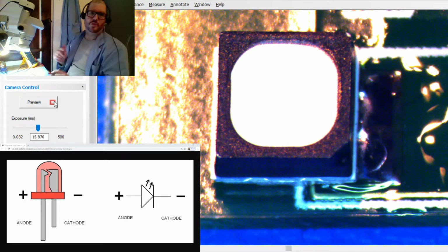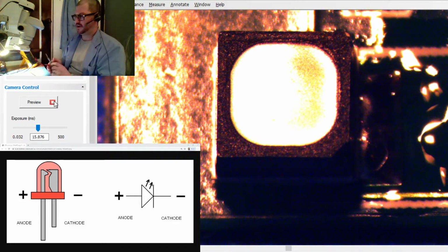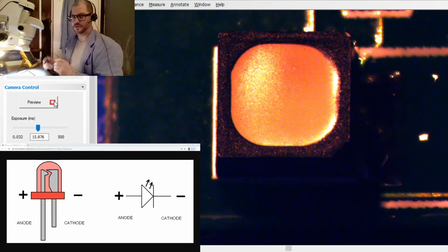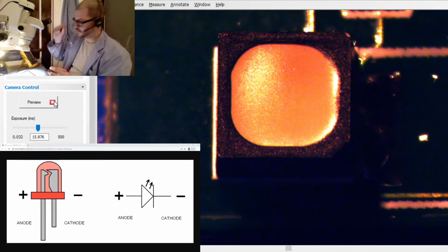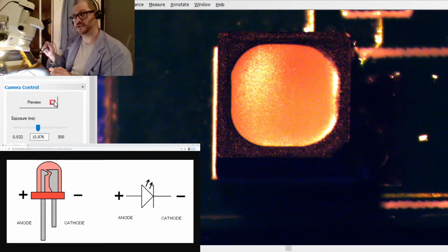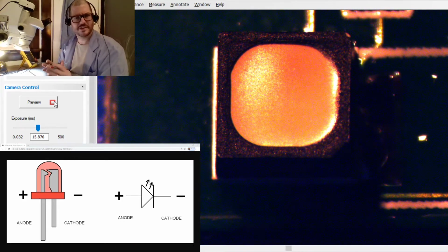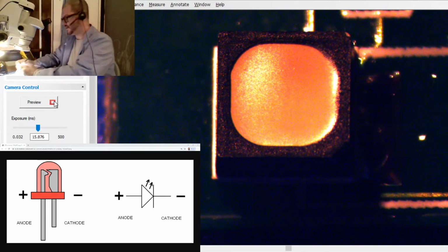This makes it easier. Number one, it makes it easier for me to put the probes down on top of the thing. Number two, I can simply put the black probe down on top of the large metal pad, so I don't have to worry about that. And two, the solder is actually holding it into place. It has melted on both the pad as well as the part, which electrically and physically connects them together. The physical part is the more important one. It's physically holding a rather small part into place.